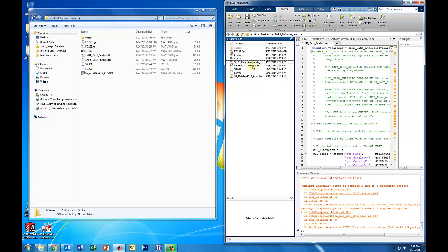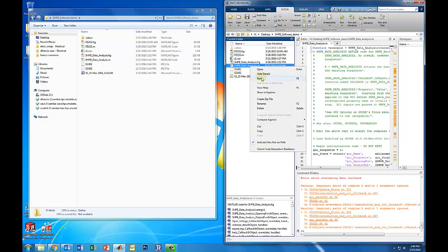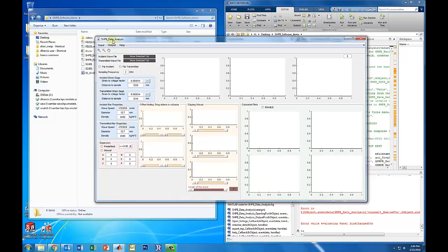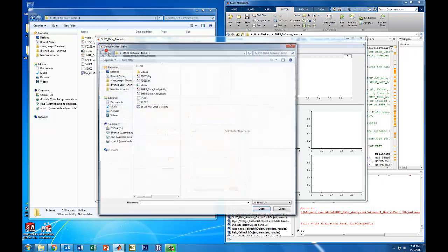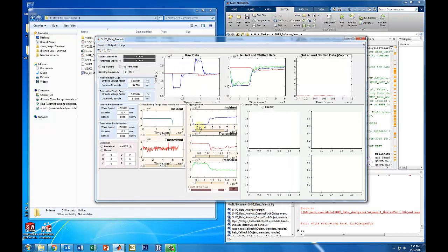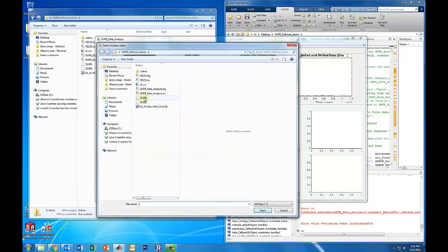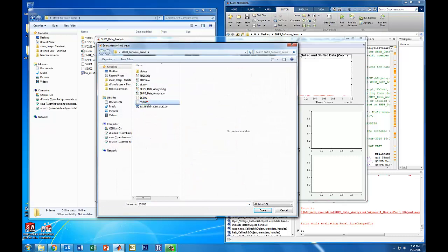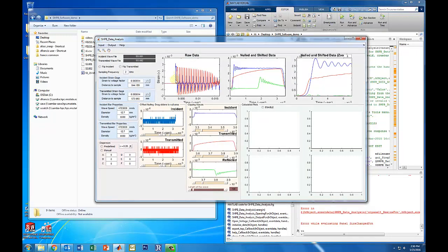So to begin with, we can run the portion which takes a voltage and then outputs a force displacement. This tool can handle various types of data. You can import your voltage files from an Excel file as long as it's formatted as 2 columns. You can also just import the voltage files, so say this is our incident voltage, and then it asks again for a transmitted voltage, brings those in and populates this data.